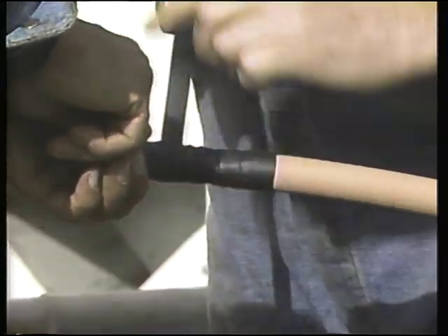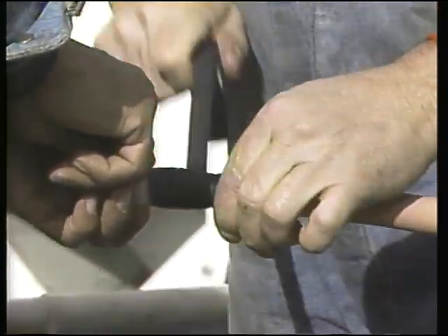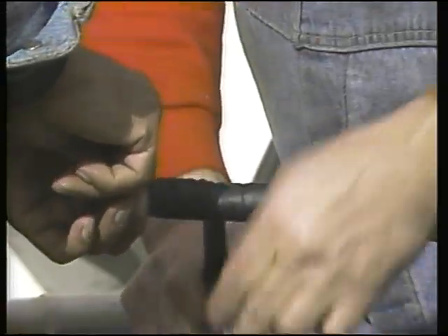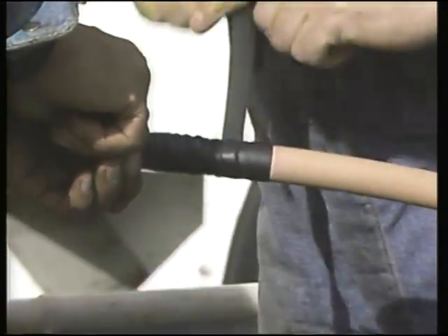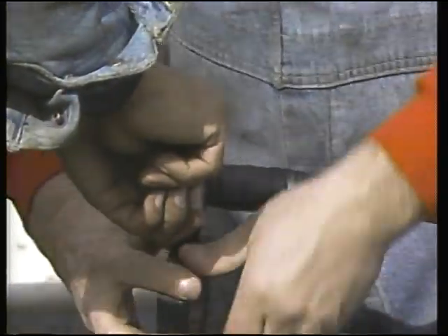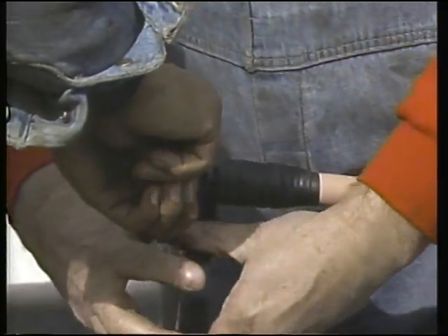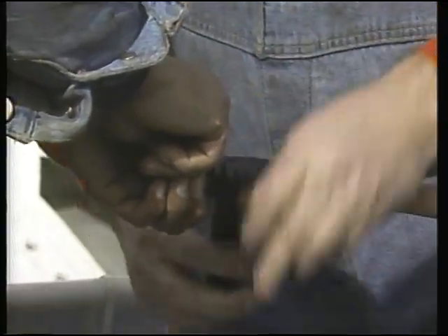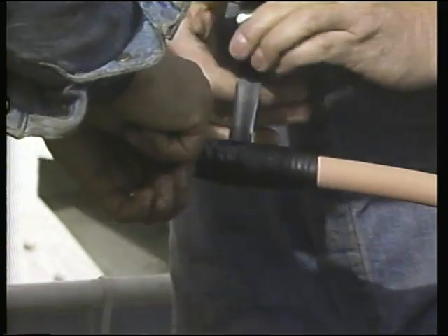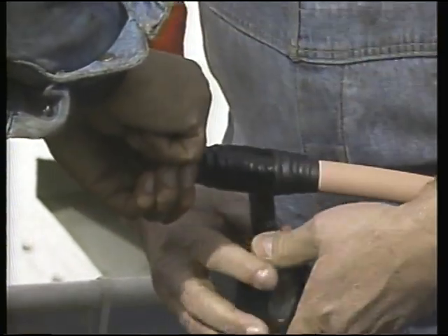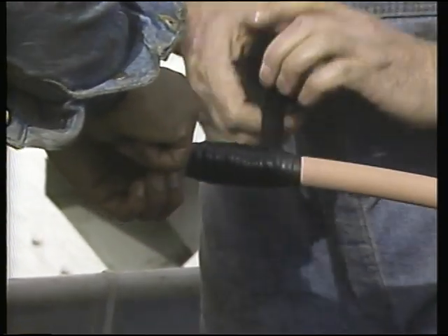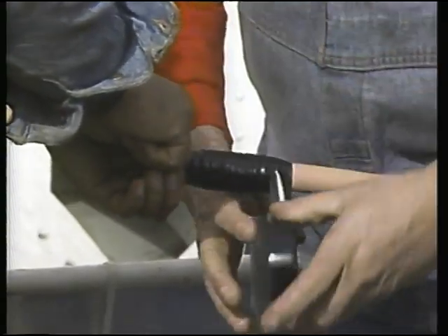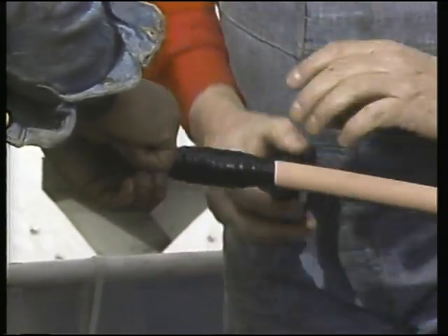The rubber tape is applied over the semiconductive tape from the connector barrel back to the top of the tapered area of insulation. When the second cone is finished, the termination is completed by reconstructing the jacket layer of the cable with 2 layers of plastic insulating tape. The first layer is applied over the entire length of the cable, from the end of the lug back to the termination point.